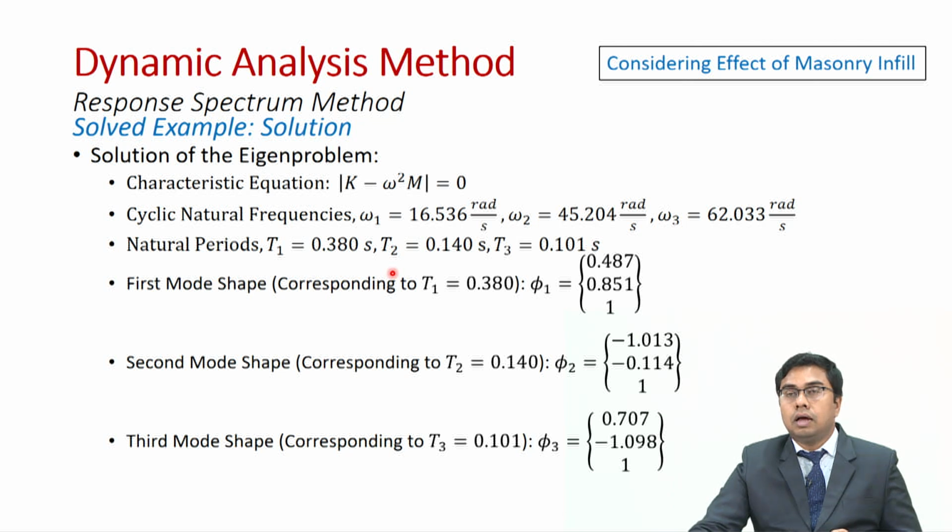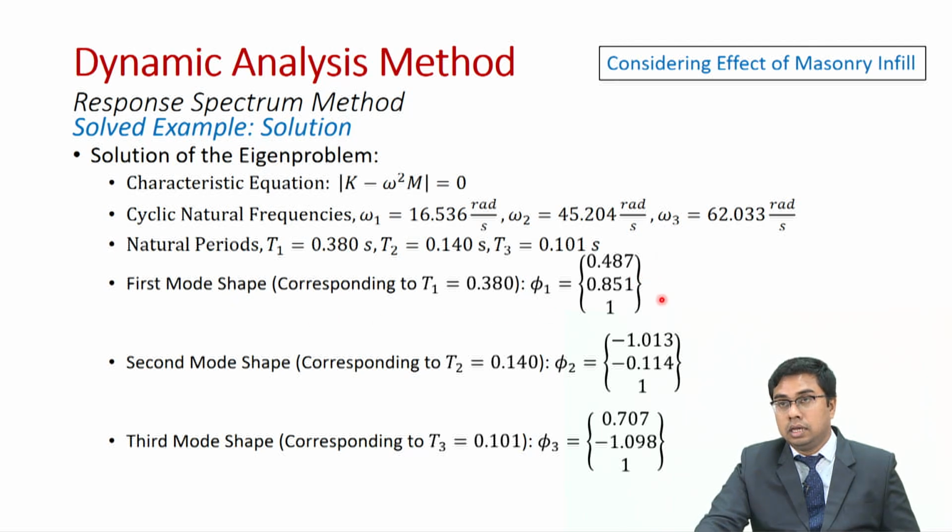So, again, after solving the characteristic equation, we are able to obtain natural period and various mode shapes, that is the modes of oscillations, which are shown over here. Again, I would like to reiterate at this point, which you might have the understanding from